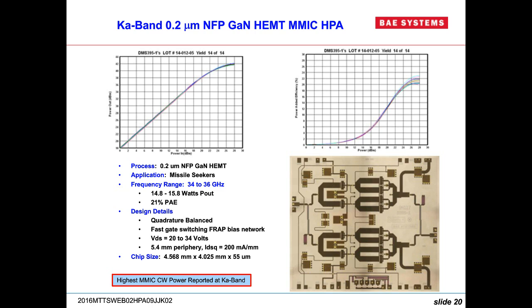This is just one of the circuit techniques that we use to match the gate side. In this particular case, because the impedances are much higher with the GaN device, we didn't have to resort to that on the drain side. If I push the power amplifier to higher power levels, I'd probably have to go to those types of structures there too. But on the gate side, it just happened to be a convenient circuit technique.